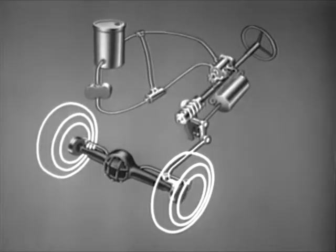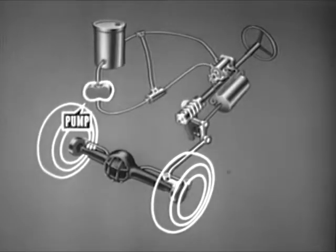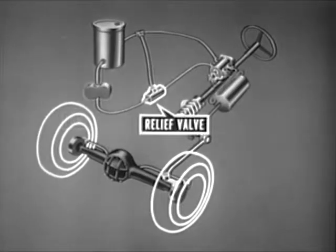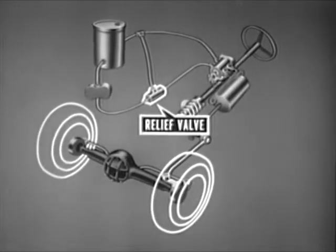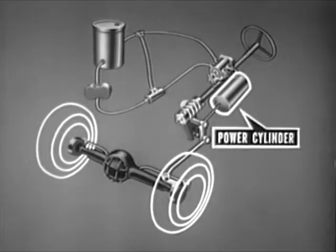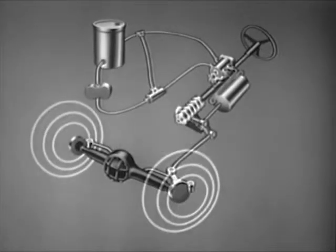Now let us review the operation of the hydraulic steering system. The reservoir supplies fluid. The pump, driven by the engine, delivers the fluid under pressure through the relief valve to the control valve. The relief valve provides an escape for excess pressure back to the reservoir. The control valve directs fluid to the power cylinder. The power cylinder converts hydraulic pressure into mechanical force, which in turn actuates the Pitman arm shaft and lever and the Pitman arm, turning the front wheels of the vehicle through the steering linkage.